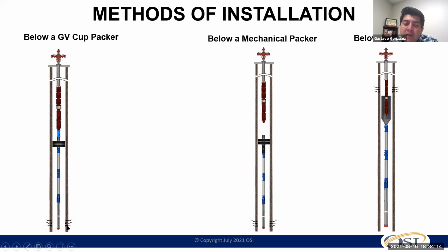So I can keep my flow path: fluid comes from the perforations, goes up, goes through the screens, goes through the desander, passes through the equipment and exits below the sensor. And now the fluid, with less volume of sand, will go around the ESP and through the intake. So that will be the isolation method that I can use.